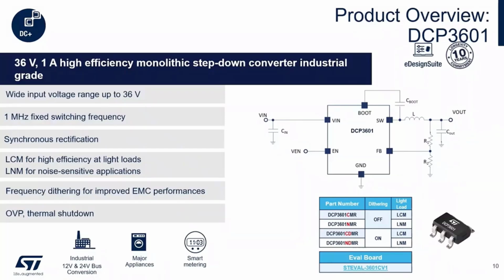This device also comes in dithering and non-dithering versions to help you by leveraging spread spectrum within the internal oscillator of the buck regulator, which helps with emissions testing.